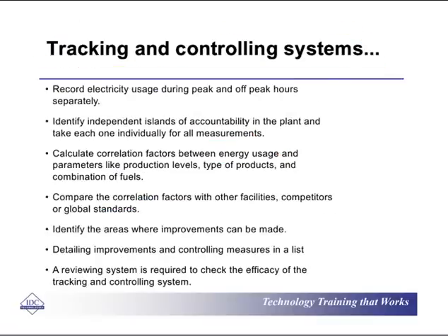Tracking and controlling systems, record electricity usage during peak and off-peak hours separately. Look at independent islands of accountability in the plant. Look at correlation factors. These show you the degree of similarity between the different parameters. So you may find that there's certain parameters that you're measuring which are highly correlated, and others there's no relationship at all. And then look at other facilities, competitors, or global standards. It's always good to benchmark, very important.